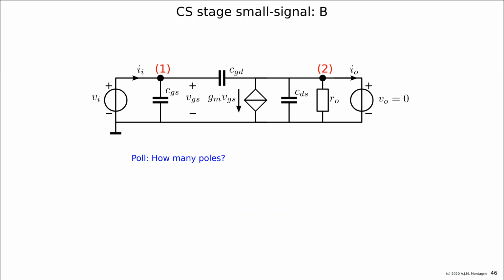Now I see again an answer like 4, but I don't see 4 capacitors, so this must be a mistake. There can never be 4 states if there are no 4 reactive elements in the circuit. I also see 3, but we already know now what is the answer. The answer is the number of independent capacitor voltages.